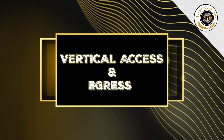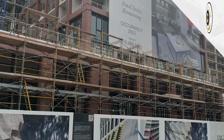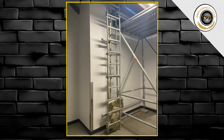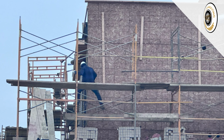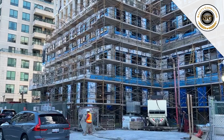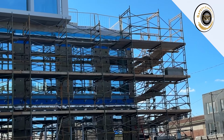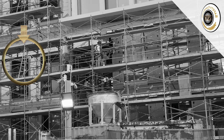Vertical access and egress. Safe access to and from work levels is crucial. Verify that vertical ladders are in place, properly secured, and provide an unobstructed route for workers. If the scaffold has hatches, ensure they are equipped with covers to close off the opening when not in use, preventing fall hazards during climbs.